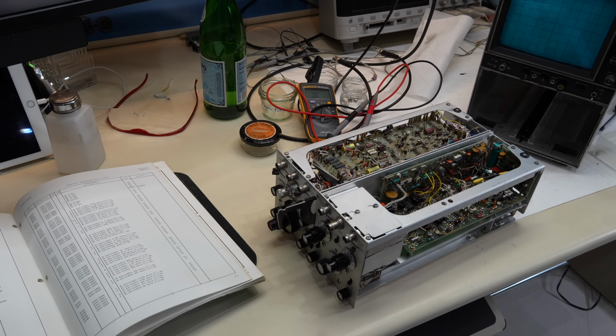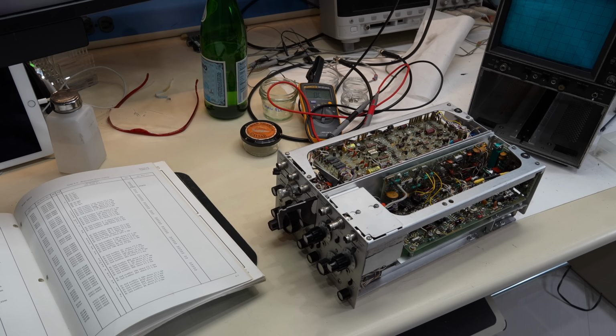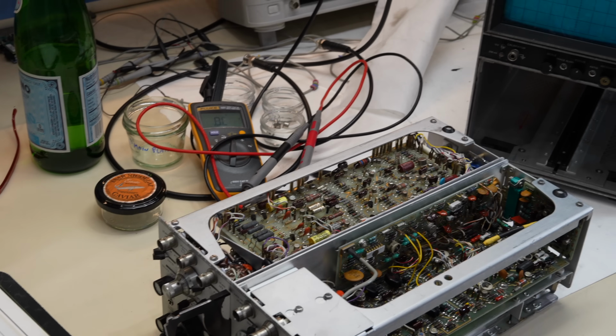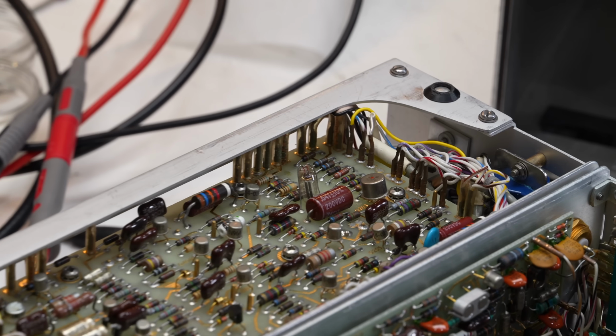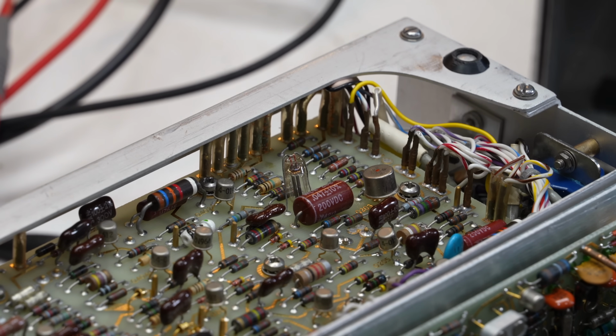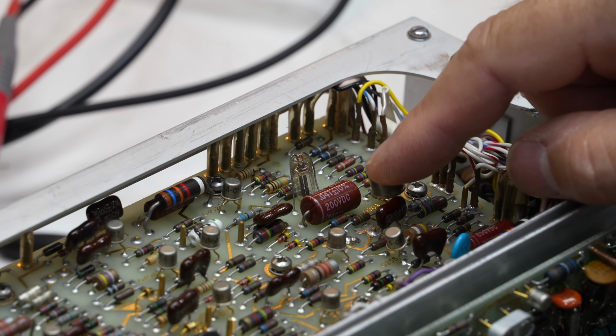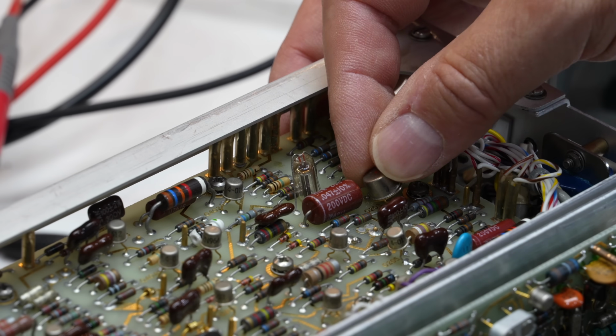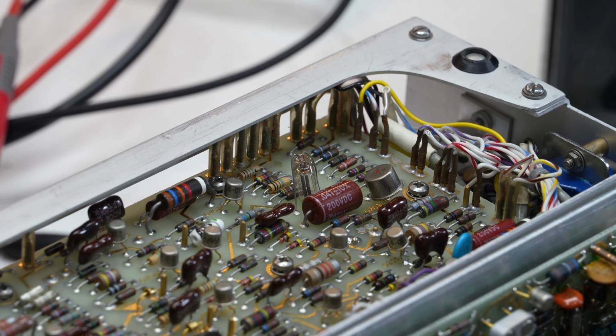You know, I was reviewing the footage and I realized that I never checked again on the transistor that was smushed over there, and that's the one that drives the neon reset light that doesn't work. So maybe it's not the neon, it's the transistor, and then I just looked at it and one wire is broken, probably from the smushing.